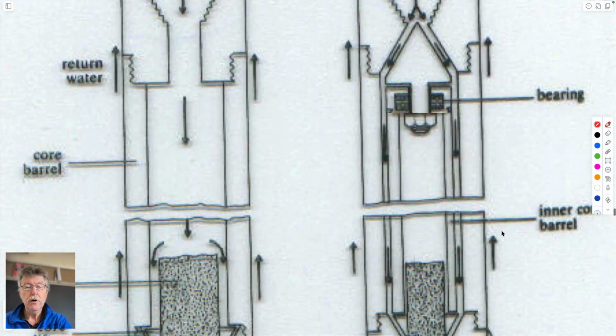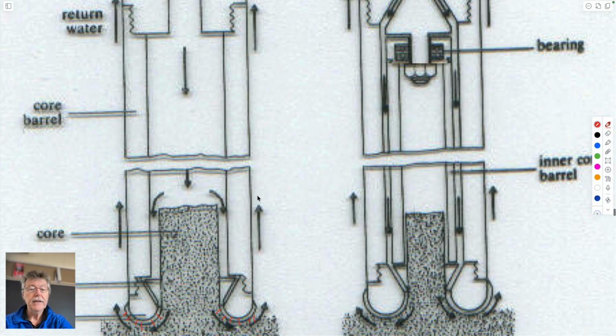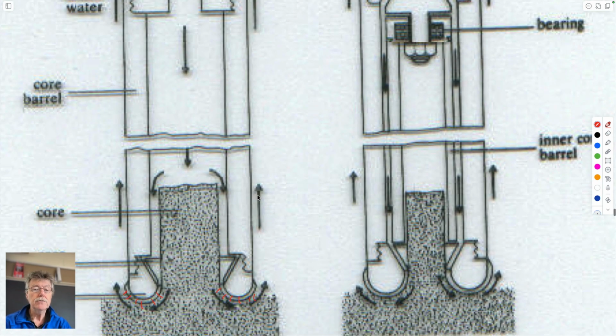In diamond drilling, the whole effort is to be able to actually recover an intact sample of the core by making it abrade all the rock in a tunnel around the cylinder that goes down. The core rises up inside the core holder. Again, just like tricone drilling, there's a drilling fluid which is circulated down through the system, takes the cuttings away from the drill bit.